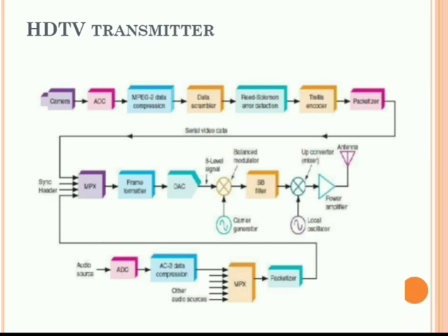The resulting symbol rate here is 10,800 symbols per second. This symbol rate translates to a data rate which, after eliminating the extra RS bits and trailing bit, gives an actual video and audio rate of about 19.3 Mbps.